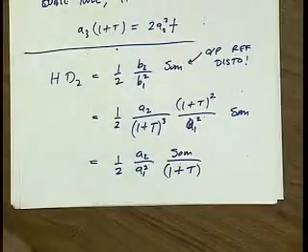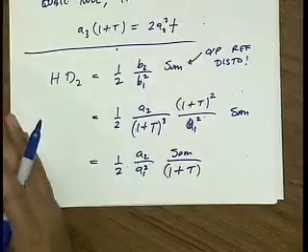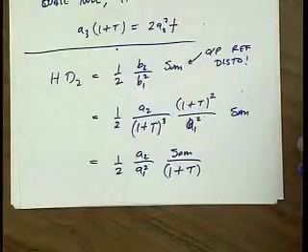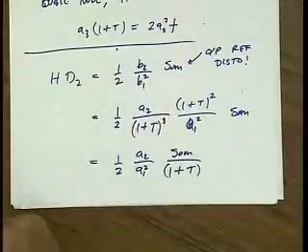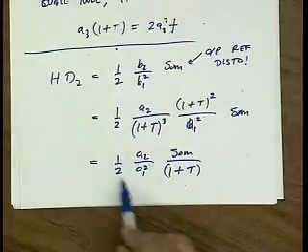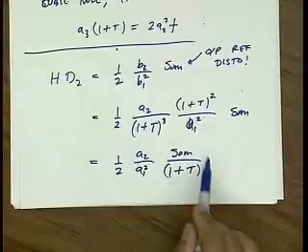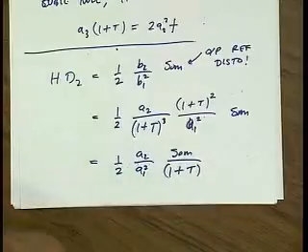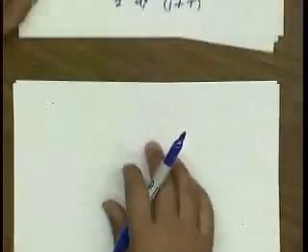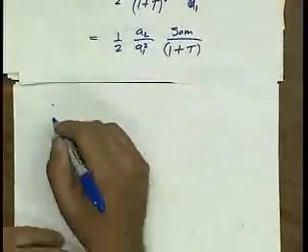Because if I just do input referred HD3, it's not fair. I can't compare my original amplifier to the one with the feedback, because the original amplifier had more gain. I've killed that gain by putting feedback in. But even though I did that, I still have improvement. The output referred HD3 gets better. Okay, very good. So that's HD2, now let's look at HD3.